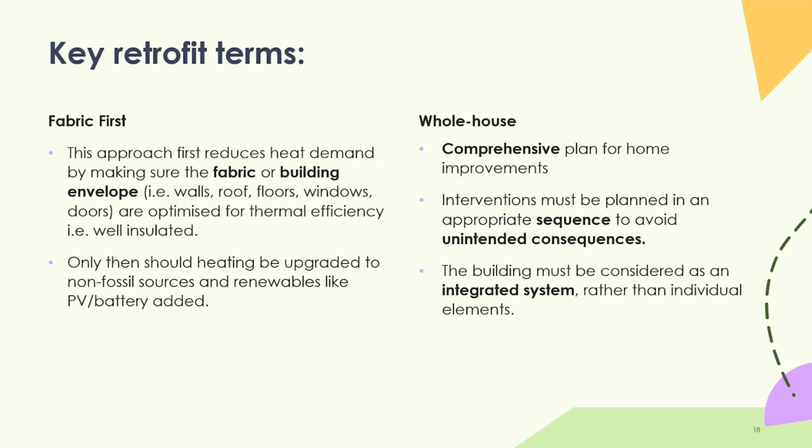For example, if you need to do external wall insulation and replace windows, it's good to do them at the same time, because if you come back and do windows afterwards, you're introducing a lot of technical risk in terms of breaching seals around the EWI, and it could get quite messy and invalidate warranties, all sorts of things that we don't really want to do ideally.